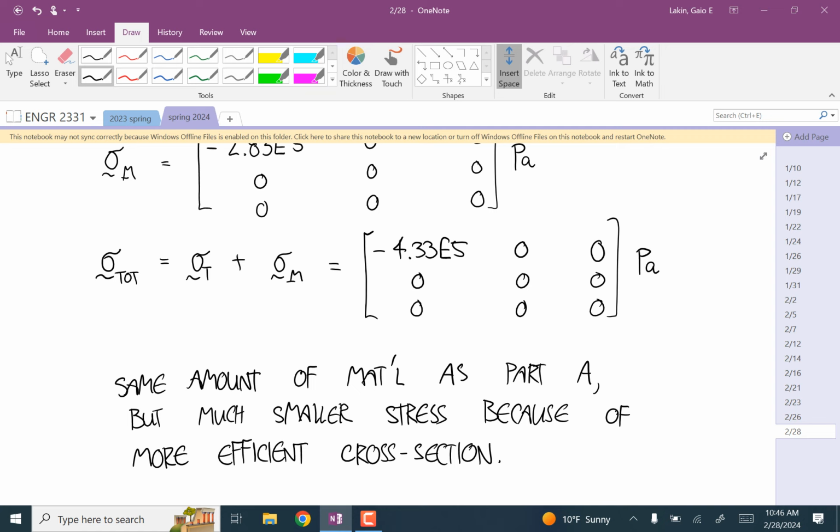It's a hollow, thin-walled rectangle. That's all we can do for everything. If you don't have torsion, then you have a lot more options. But torsion is the one that, like, we've already limited our options somewhat, and then torsion is going to limit it a ton. So, yeah.